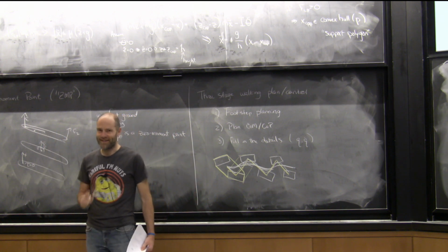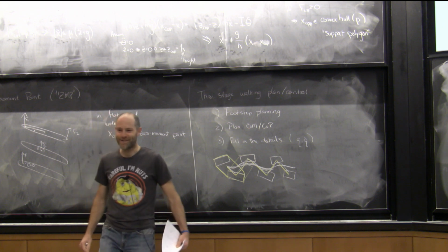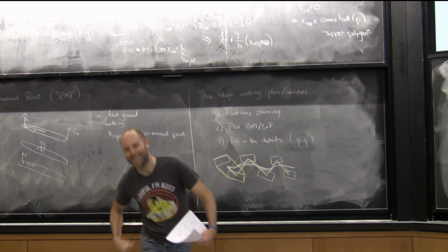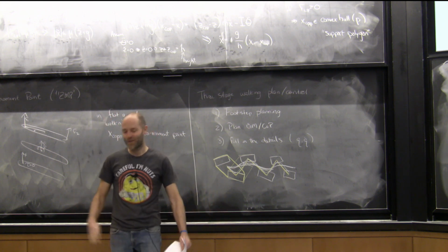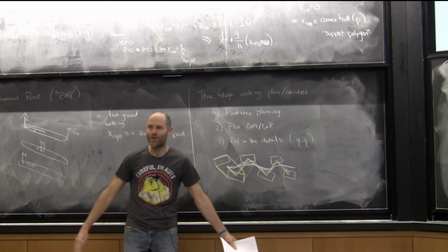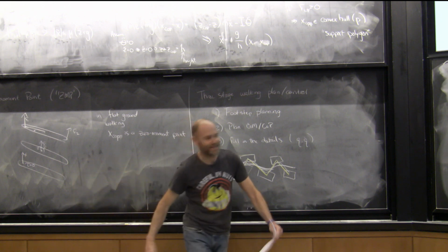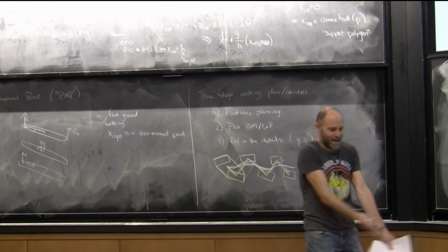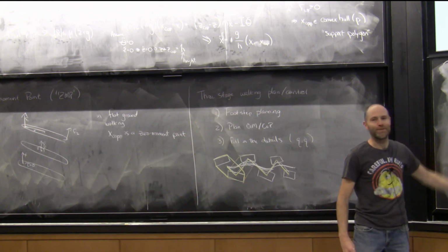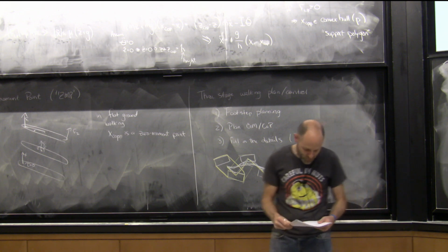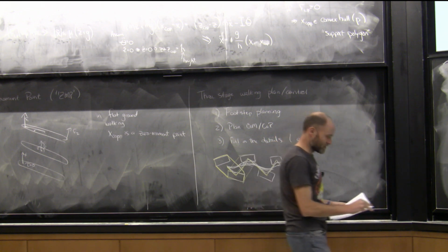It's very rare to see someone, when the robot's like this, push it this way, because it has to cross its legs. The quadrupeds are fine. They've got no legs to get in the problem. But the humanoids have a hard time with that because there are all these kinematic constraints and you can't do simple heuristics like this. Okay, something to watch out for.